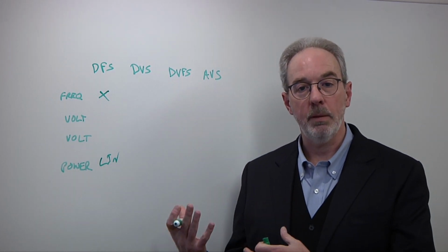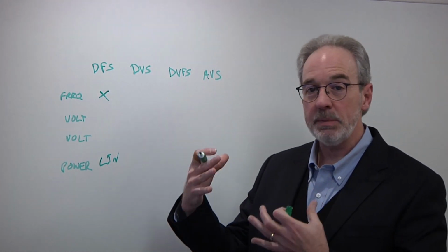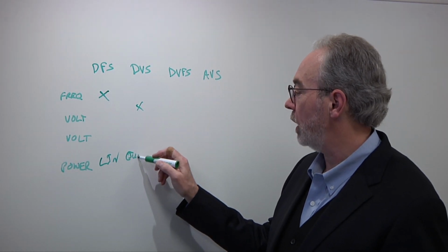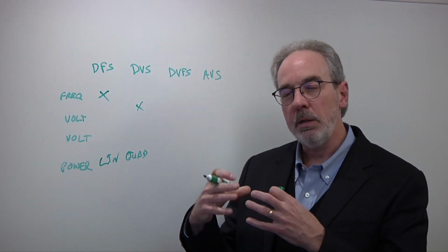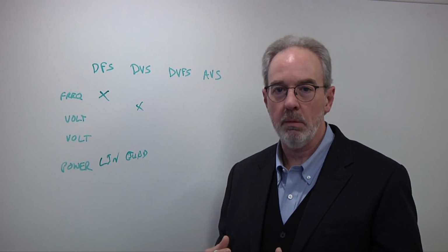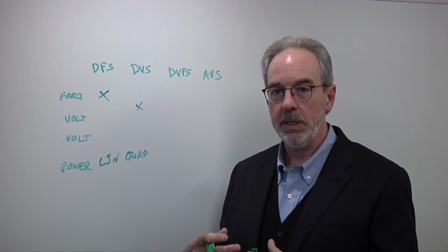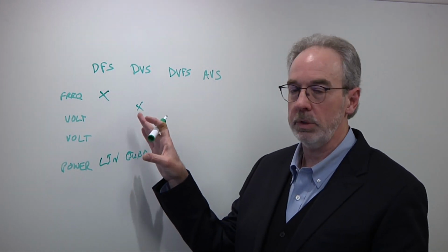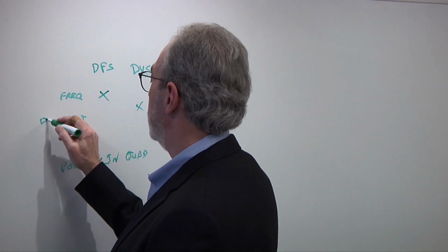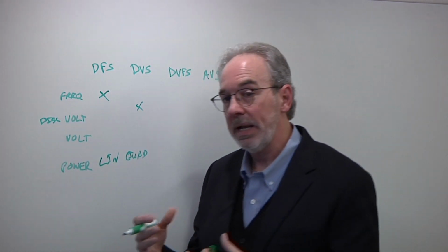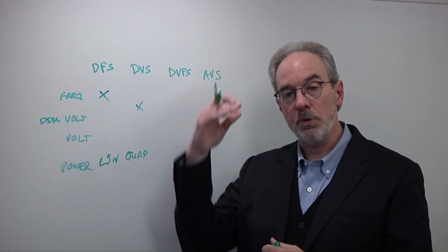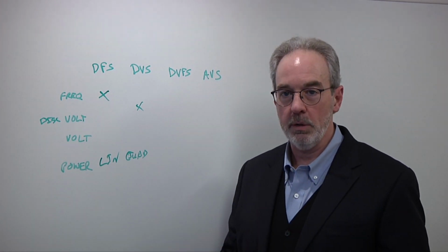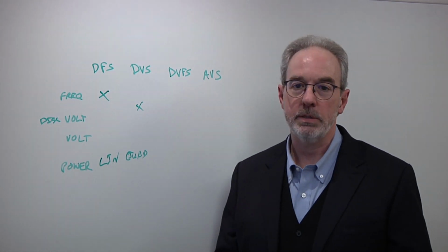As we move on to dynamic voltage scaling here, it's the same technique. You're manipulating the voltage. And remember, you're getting a quadratic improvement here. The difference is that DVS is a bit more complicated to deploy than just changing the frequency. And in fact, what we typically see is people not continuously monitoring or adjusting the voltage, but doing it in a discrete fashion. So you'll decide either at design time or on the tester a number of discrete steps, your DVFS states, and then you'll flip between those on the fly as part of your DVS solution.